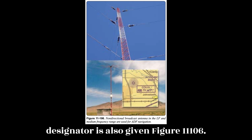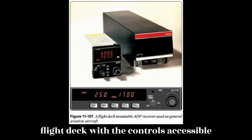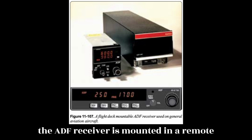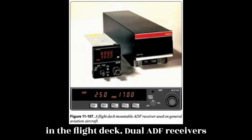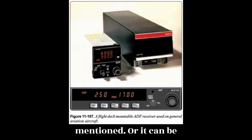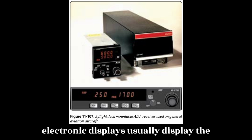Figure 11.106. ADF receivers can be mounted in the flight deck with the controls accessible to the user. This is found on many general aviation aircraft. Alternately, the ADF receiver is mounted in a remote avionics bay with only the control head in the flight deck. Dual ADF receivers are common. ADF information can be displayed on the ADF indicators mentioned, or it can be digital. Modern, flat, multipurpose electronic displays usually display the ADF digitally.